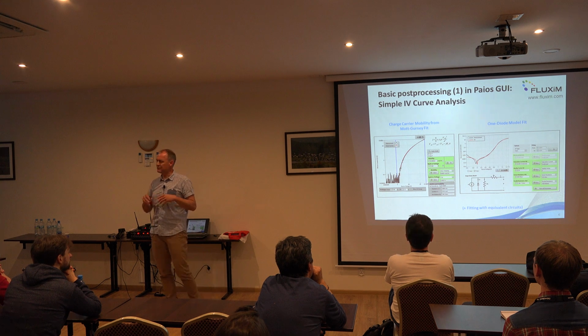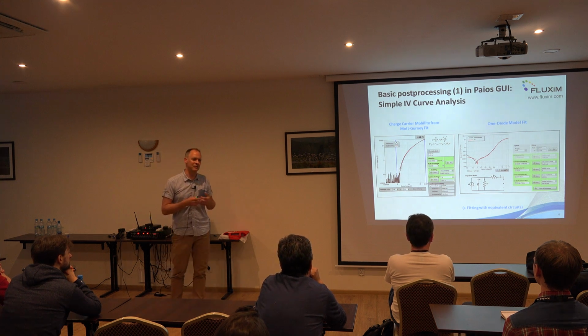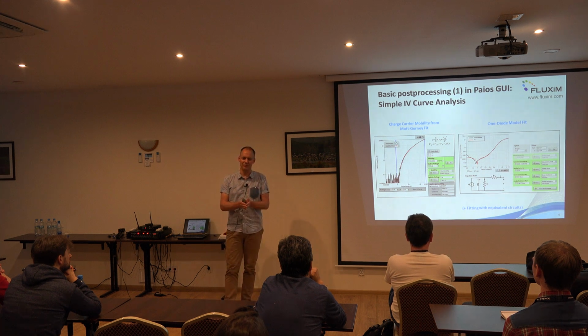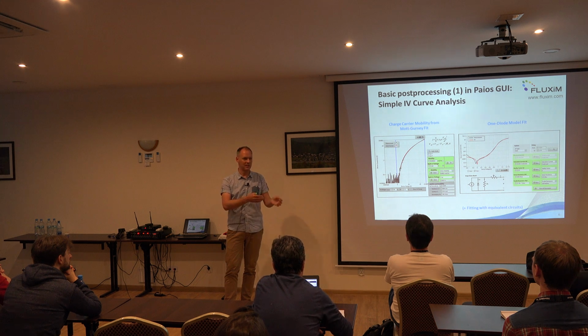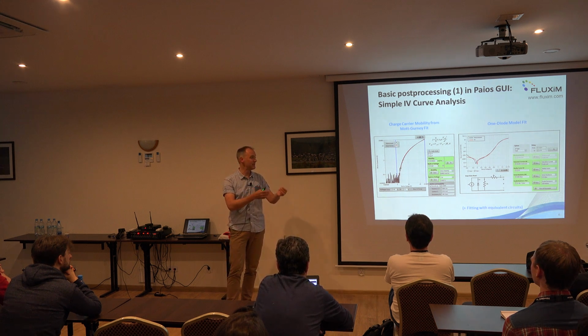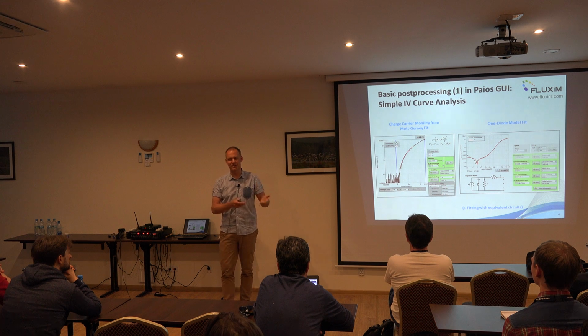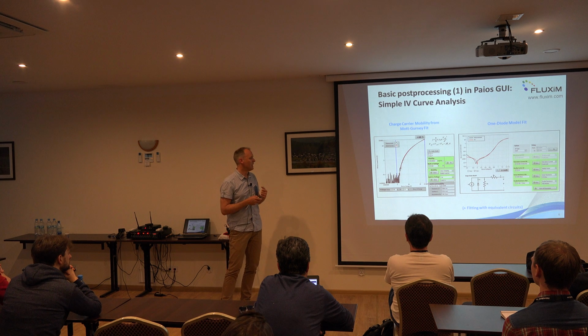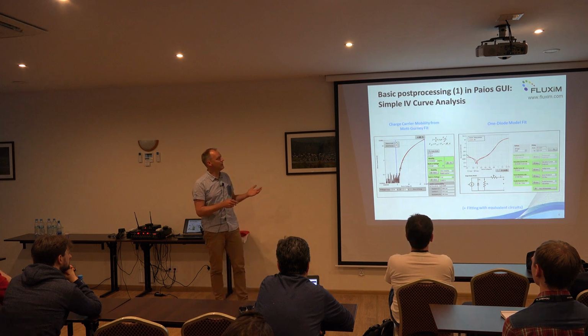Now, after you've done a measurement, there are always 2 categories of analysis. Either you play around with simple formulas just to detect a peak, and from the peak position assign, let's say, a dynamic transient: take a peak position, assign a transit time, estimate mobility. We call that basic processing. Another example is the Mott-Gurney fit.